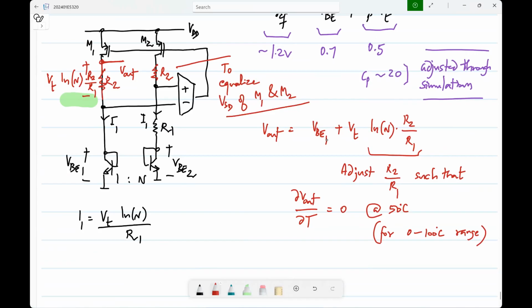Any questions about this? This is called the standard band gap voltage reference. And if you have played with circuits for any hobby related stuff, you may have seen band gap voltage references, or at least voltage references which have a value of 1.2 volts. The reason it's 1.2 is that it is coming from the band gap voltage reference. And for any other voltage, you essentially make this and either attenuate it by some fixed ratio or amplify it by some known ratio.